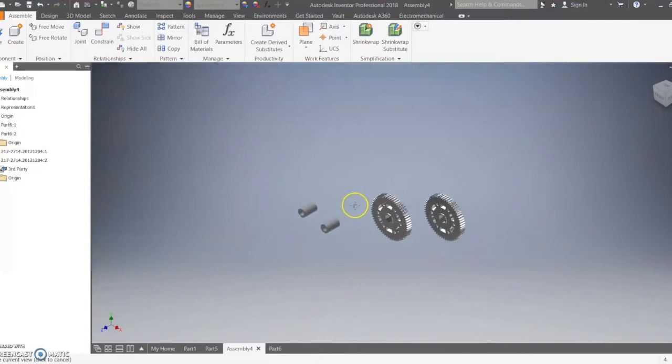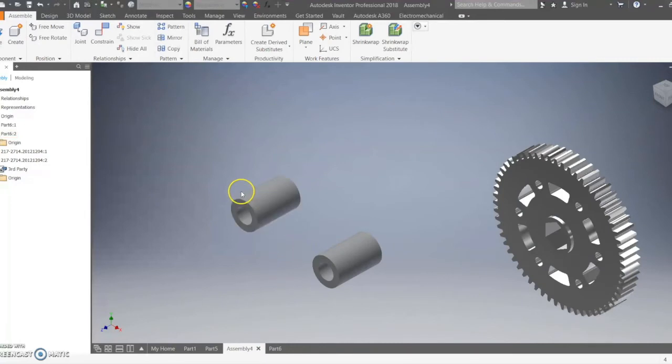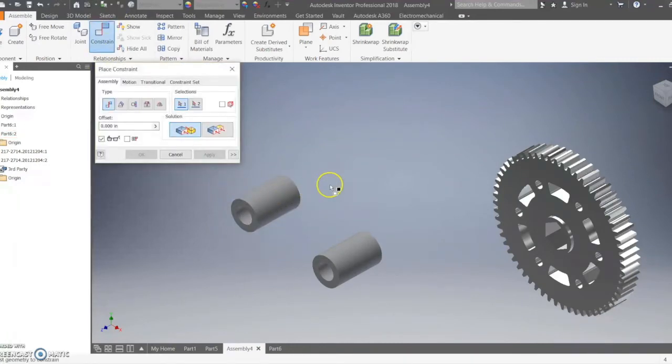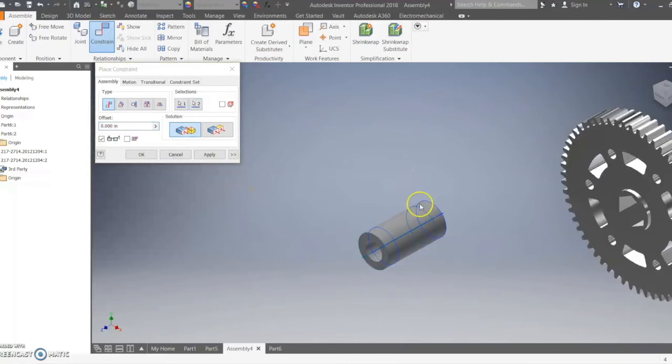There are a few more types of constraints that are very common. Of the most common are the circular constraints. Circular constraints use circular references as a reference point to constrain one object to another. For example, if you had a bolt in a hole, you would constrain the bolt through the hole using circular references. There are 2 types of circular references. First, you have the pathway, which basically takes the circular path all the way through, and it constrains it with the circular path of another object.